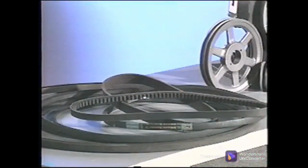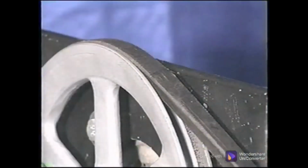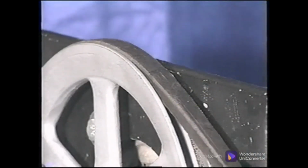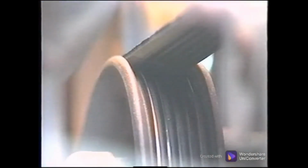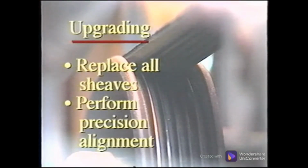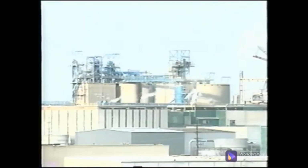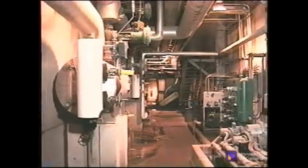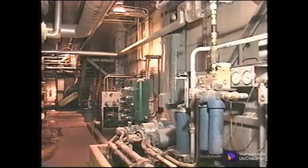The lowest rated of these belts, the standard V belt, is the most common in industry, partly because it will stay in the sheave and transmit power with minimal effort on our part to provide precision operating conditions. To upgrade to the poly V belt, for example, means replacing all the sheaves in a drive and ensuring precision sheave alignment, because the poly V belt is less tolerant of sheave misalignment. The costs of dollars and labor to upgrade can make it prohibitive. As new machines are designed and added in the plant, they should incorporate some of the best power transmission sources.